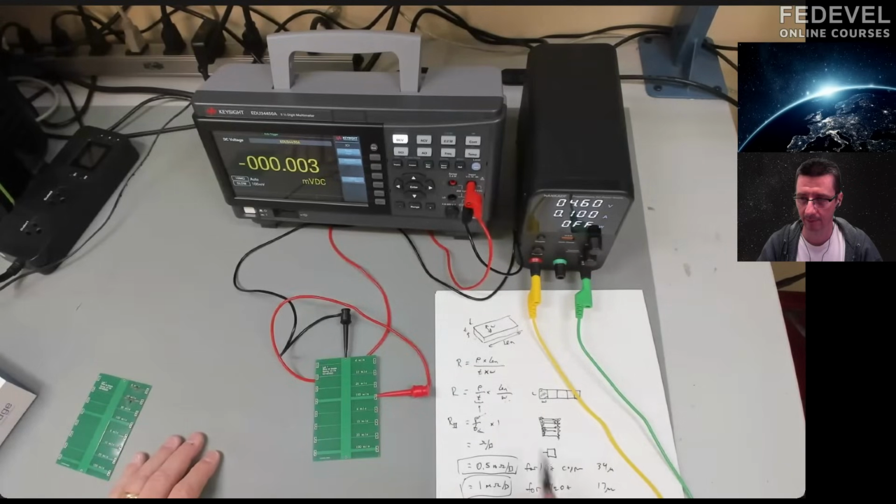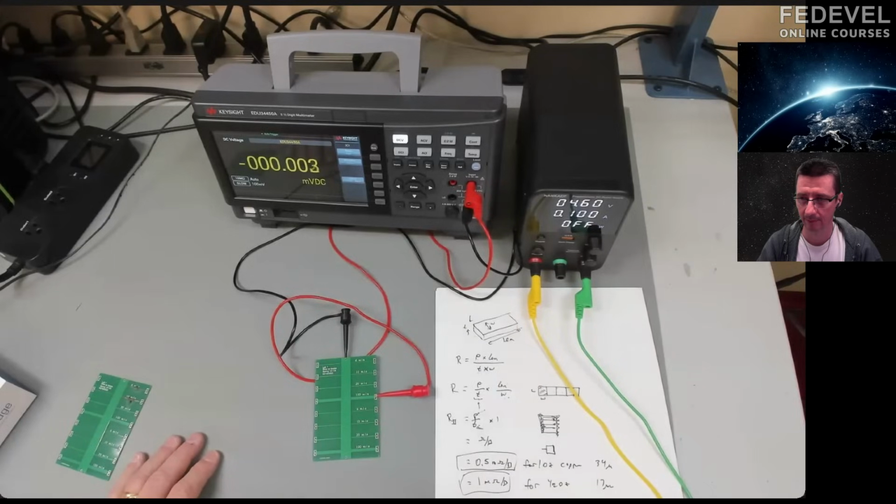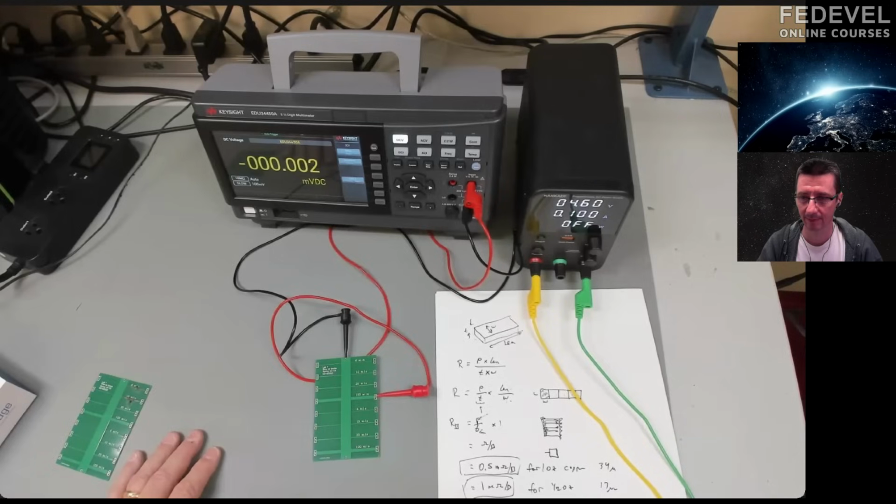Here's the crazy thing. The resistance of a trace now, I'm going to rewrite it as the sheet resistance per square, times the number of squares. If I have 1 square, the resistance of that square from edge to edge is just that sheet resistance, half a milliohm or 1 milliohm, depending on the thickness of the copper. That means if it's 10 mils on a side, or if it's 10 inches on a side, edge to edge, I still have 1 square from one end to the end. The trace resistance is exactly the same. That, I think, is startling.